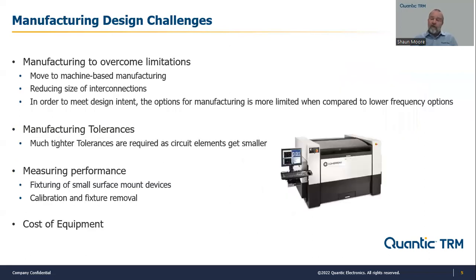Absolutely, and just like from a design standpoint, where we have to deal with precision, I think precision relative to a wavelength is probably a good way to think about it, because as the wavelength gets shorter and shorter, what is a perfectly acceptable level of detuning due to a manufacturing variance now becomes a very appreciable proportion of wavelength, in which case that can cause some major issues with yield.